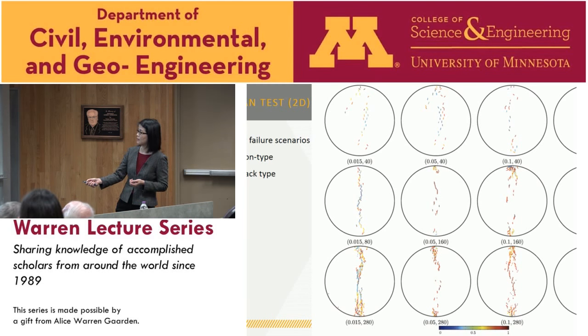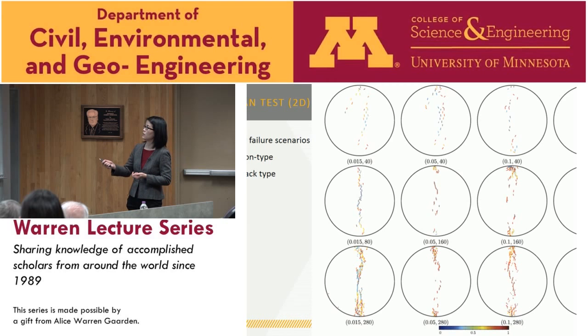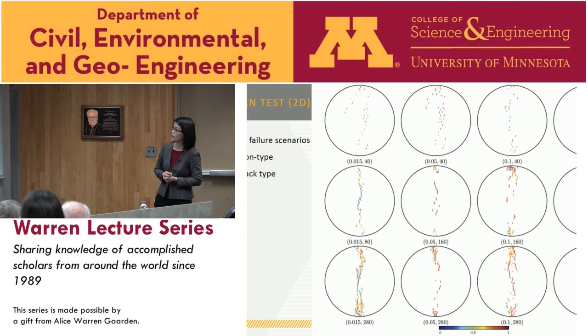With the elasto-perfectly brittle contact laws, the cracks start from the loading area in a cluster, which you can interpret as a plastic zone. Growth of the plastic zone then drives the development of tensile cracks. This is similar to an indentation type of failure. So again, with a perfectly brittle law, you have this indentation type of failure.